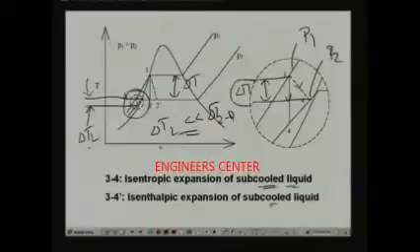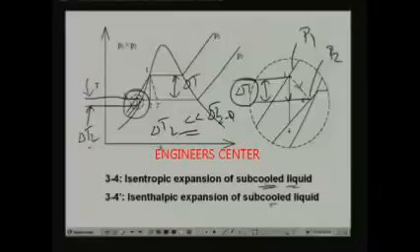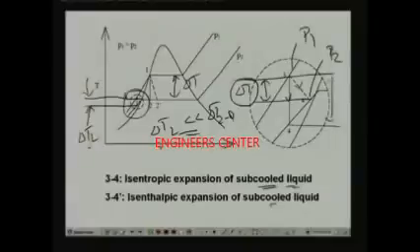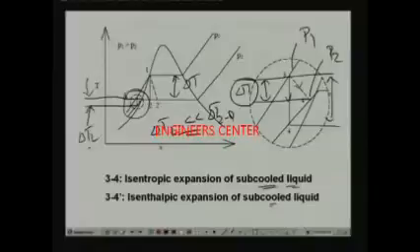Okay, so this delta T, which is the temperature drop produced when you are using a throttling device in place of a turbine, is much smaller than the temperature drop that you would get when you use a turbine. That means there are two changes compared to the earlier case. First, the magnitude of the temperature drop for the same pressure drop is very much reduced now, and unlike the previous case, here the nature of the process also affects the temperature drop. If the temperature drop takes place in a turbine, it will be slightly higher compared to the temperature drop that takes place in a throttling device.